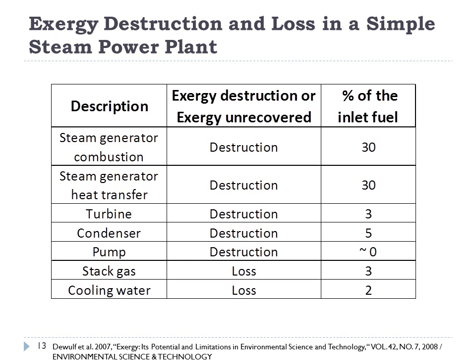Of course, to do so means putting in a lot more and larger heat exchangers, and there's going to be a capital cost to doing so. As we'll see later in the course, there's normally some kind of optimum in which you don't want to leave too much energy in the stack gas, or else you could still be getting more power from your power plant.